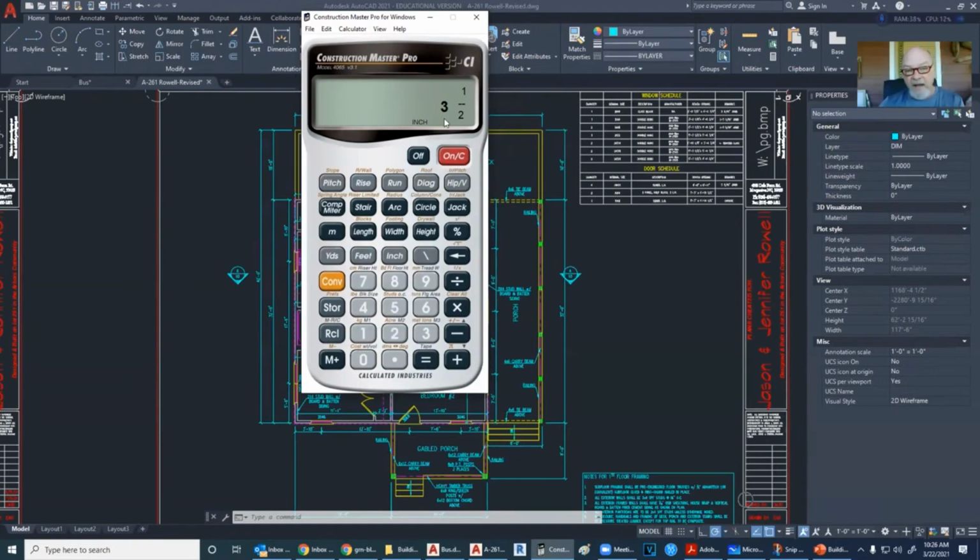Well, if I have a 3.5 inch stud and I add a 1/2 inch of drywall on either side, then I end up with 4.5 inches. So it's almost impossible to get rid of that 1/2 inch because we're working with 3.5 and 5.5. So if I had 3.5 inches and I had 5/8 inch drywall on either side, then I end up with 4 3/4.